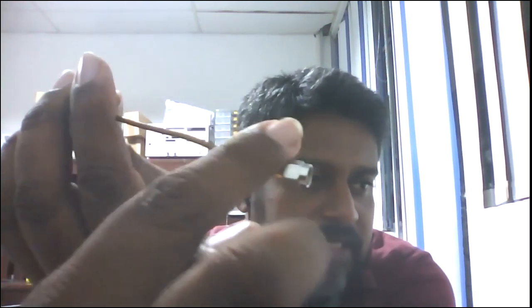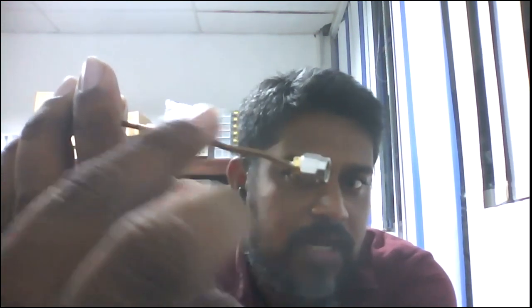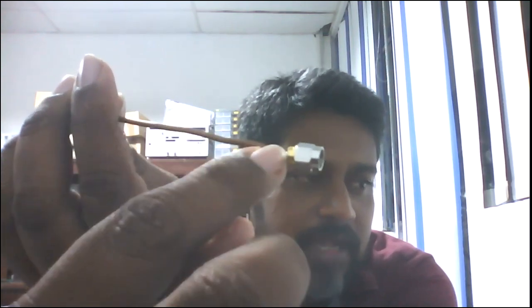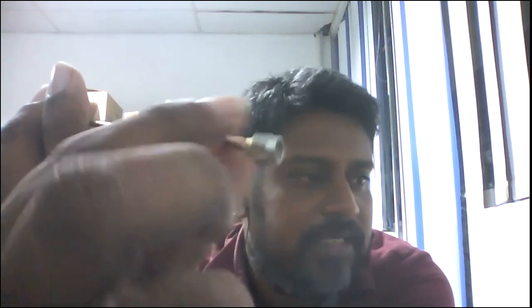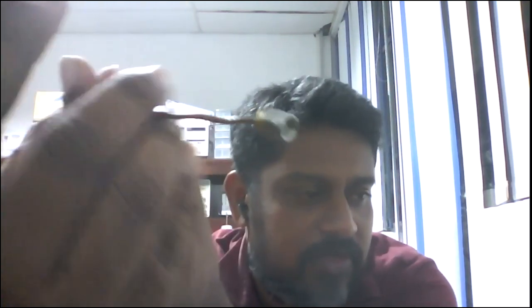So once you design the antenna, if you are using this connector, when you are designing this antenna, the antenna input impedance should be equal to 50 ohms. Otherwise, you can't directly connect this connector to the antenna. When we are designing the antenna, we can design it for any input impedance. To change the input impedance, we can match it. We can't design, actually, we can match it somehow. There are some techniques actually, so we will learn them.